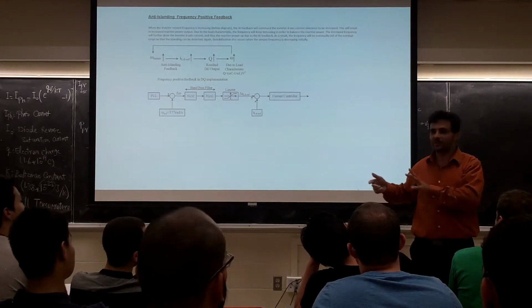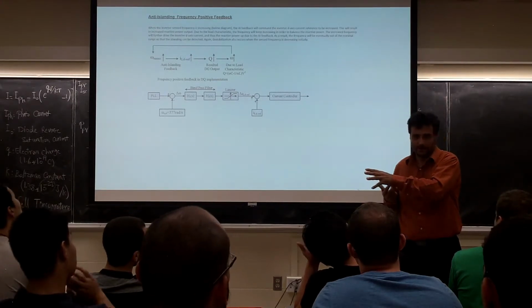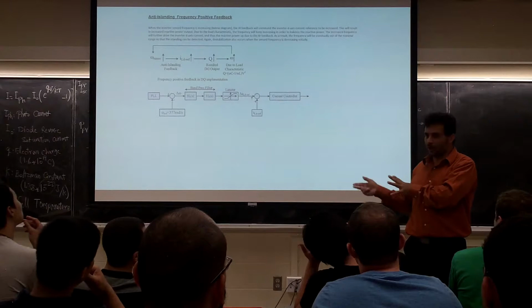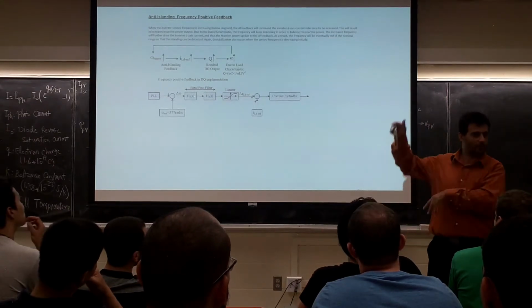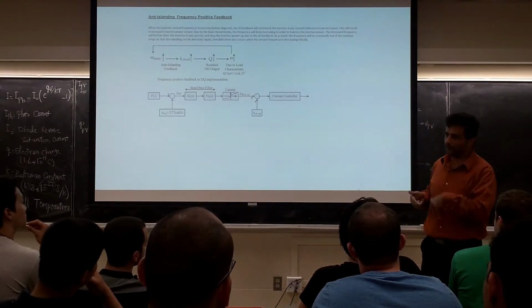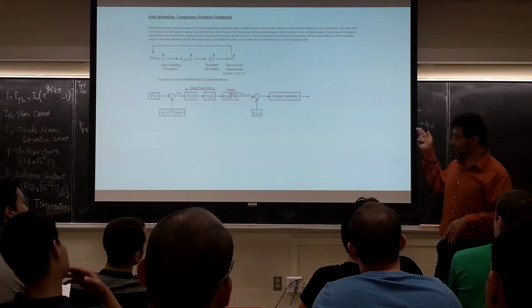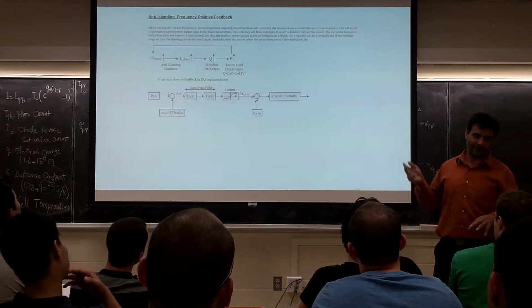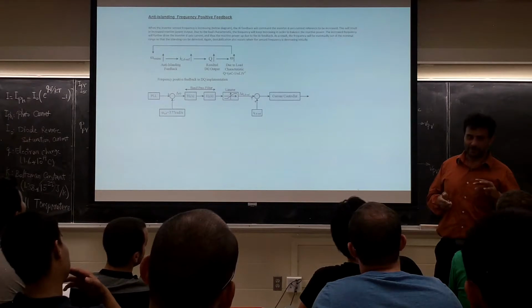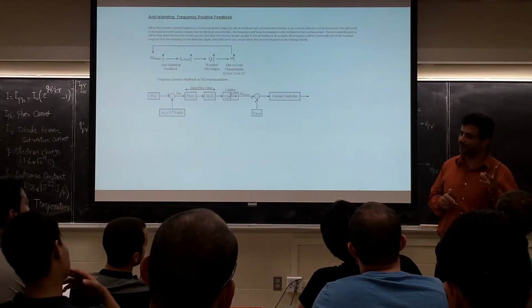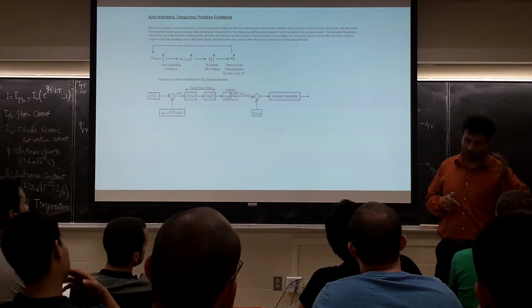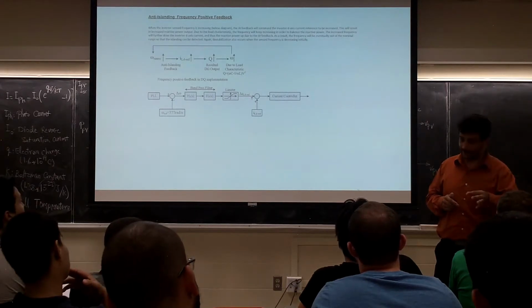This is like a fake grid. The grid is not there, but your inverter thinks, oh, the voltage is there, I'm going to keep generating power. Now there is an algorithm they call anti-islanding. Anti-islanding recognizes the fake from the real. What it does usually is like this.